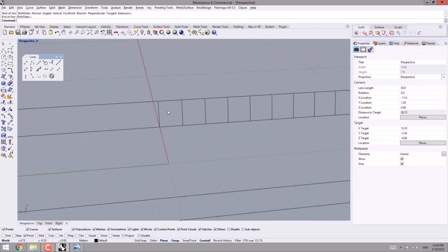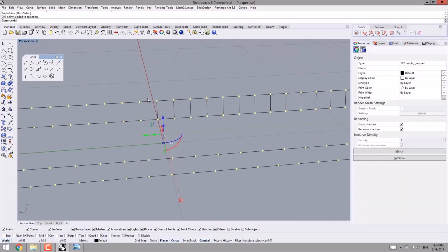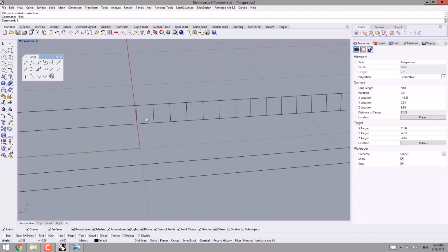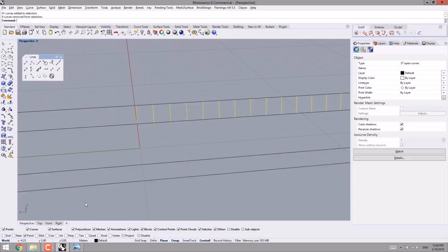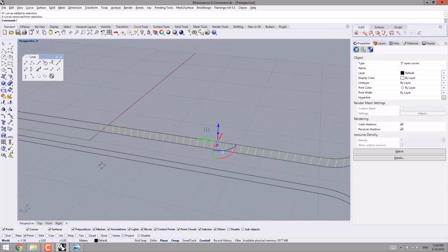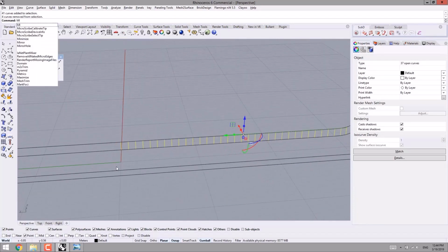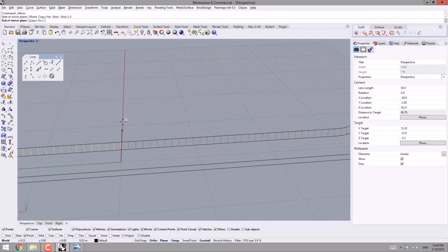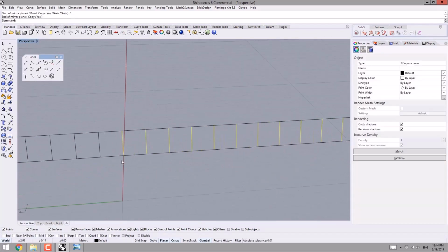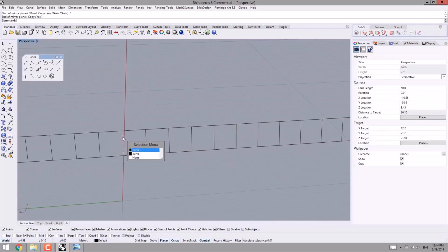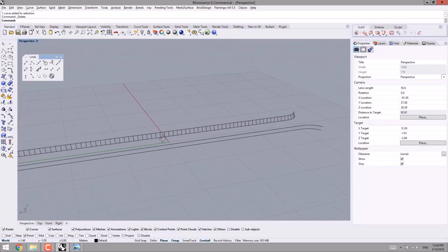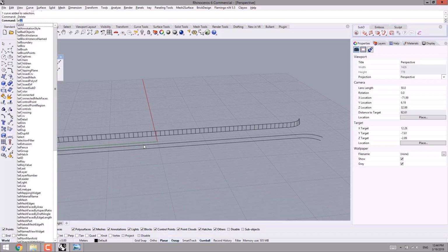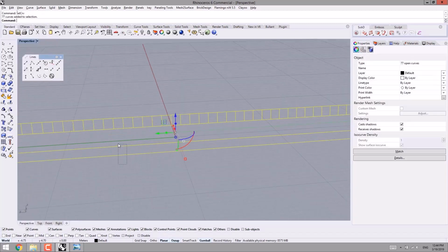I can select these, and then before using the mirror command, I use Ctrl H to hide the points. Then I select the curves, SELCRV, but I deselect the parallel lines or the main lines. Then by using mirror, I specify the end of the mirror plane like this. Here I delete the overlapping line. Again, I'm going to select the curves. Again, deselecting.